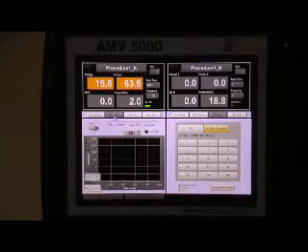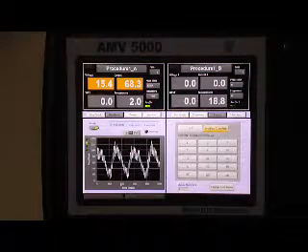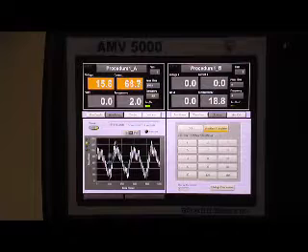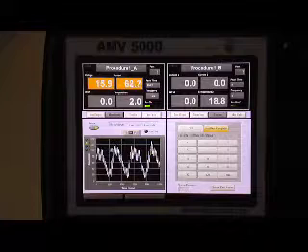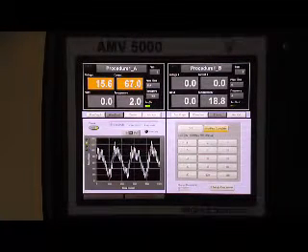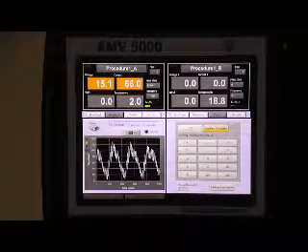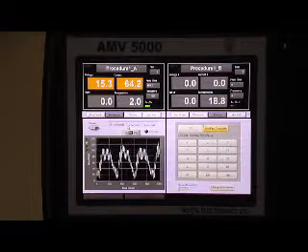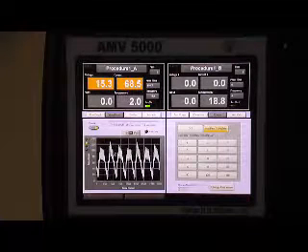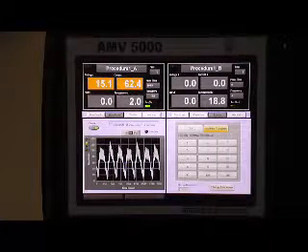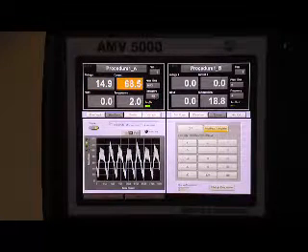If we actually look at the waveform, turn on the current, pause it, we'll see it has this superimposed 50 Hertz signal on it, but we've got roughly 1, 2, 3 and maybe a half cycles as we're going along. Pause it, and then if we look at it over a 2-second period, we've got 1, 2, 3, 4, 5, 6, 7. So 7 cycles, a frequency of about 3.5 Hertz.